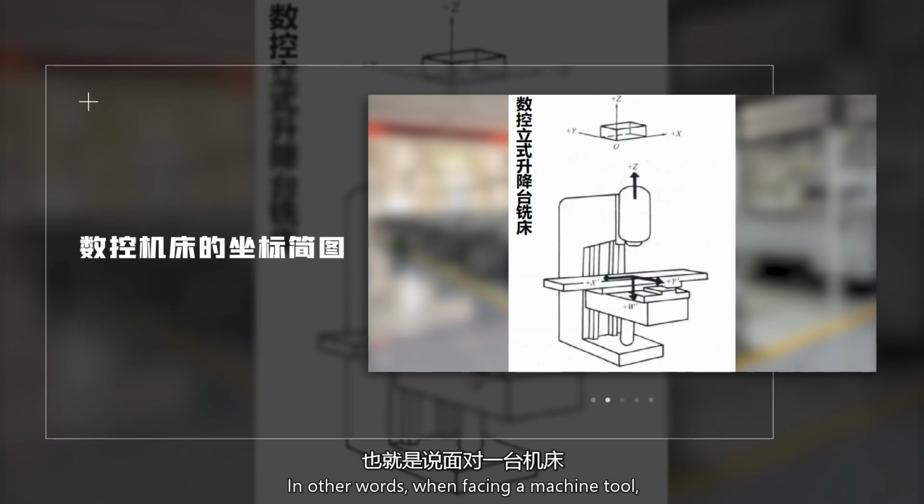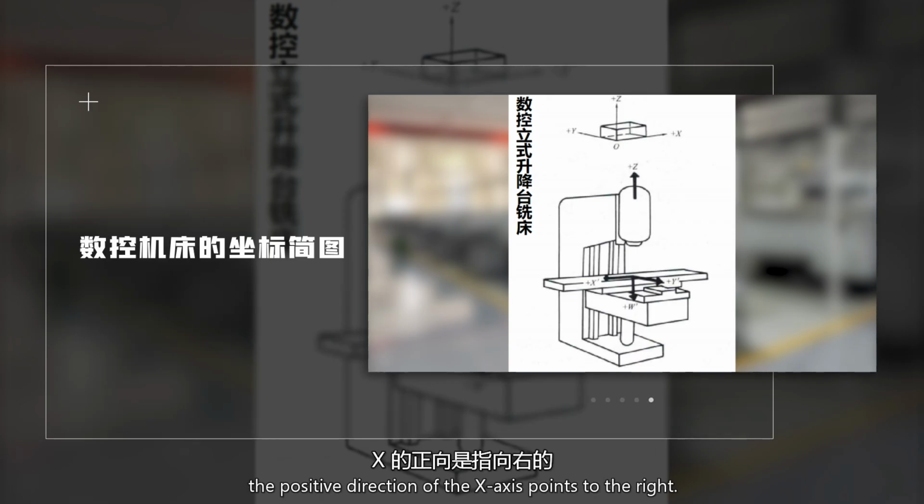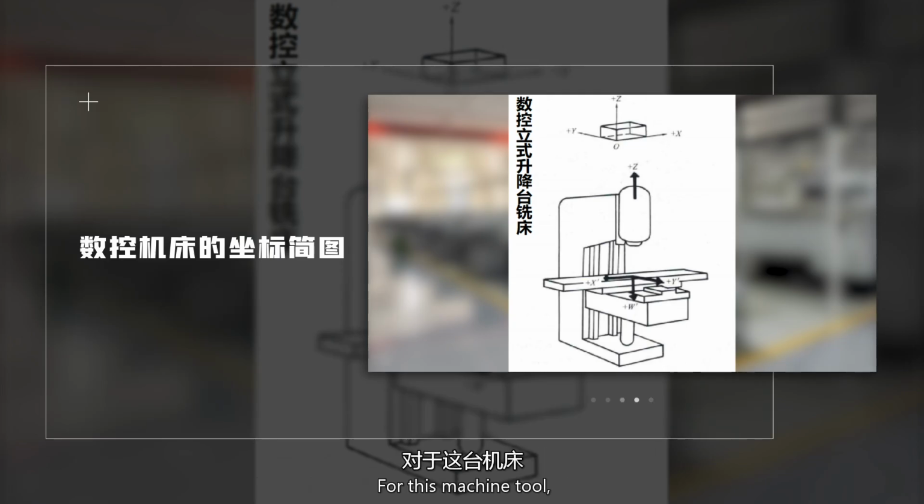In other words, when facing a machine tool, looking from the spindle towards the column, the positive direction of the x-axis points to the right. For this machine tool, the x direction is horizontal and points to the right.